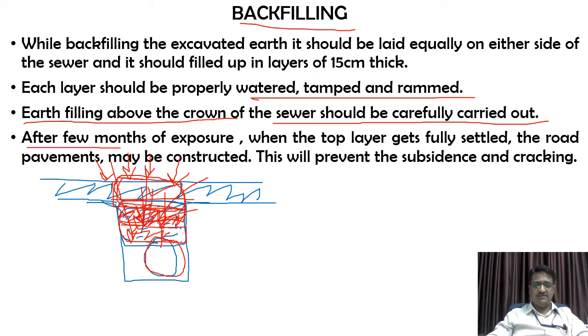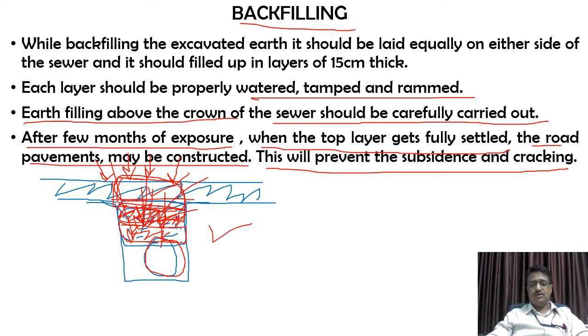Last point, after a few months of exposure, when the top layer gets fully settled, the road pavements may be constructed. This will prevent subsidence and cracking. So just now what I have explained, if you don't want any kind of sinkhole to be created, then you need to provide a lot of time for this soil to settle down. Then only the further construction on top of that is preferred. Okay, so this is regarding the backfilling of soil in the laying of sewers.